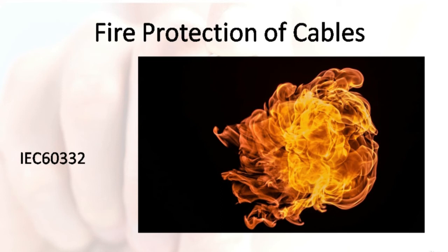Now, if there's any place where I would recommend, if you want to have extra fire protected cables, you should install it in these areas, as these are what we would consider high risk areas of catching fire and spreading fire.